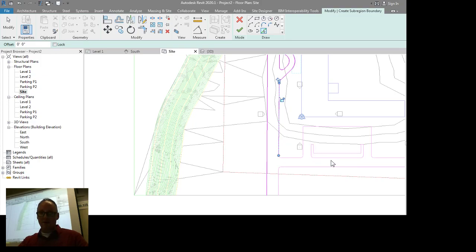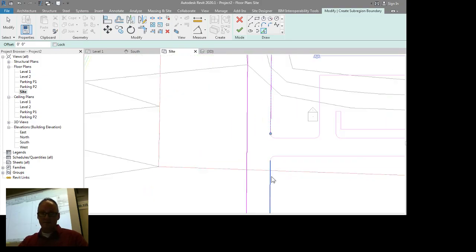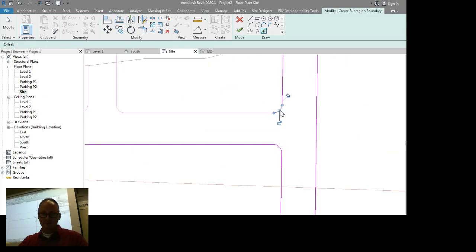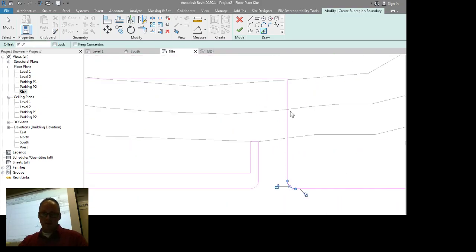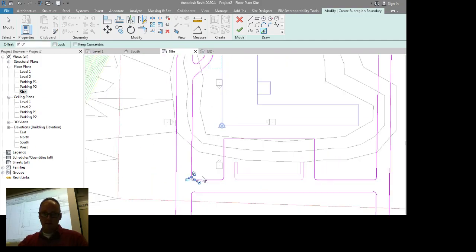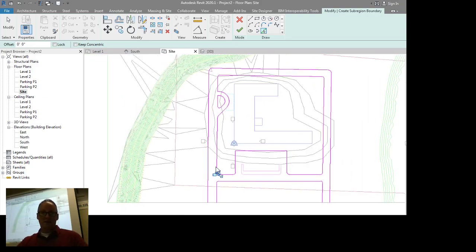And so we'll keep this simple. I'm going to ignore this island in the parking lot. So I'm picking all the curves, including the parking lot here, just ignoring the island in the parking lot. So you should see roughly this on your screens. Now you'll want to make sure that you don't pick any of those lines or arcs more than once, because that'll create trouble for you.